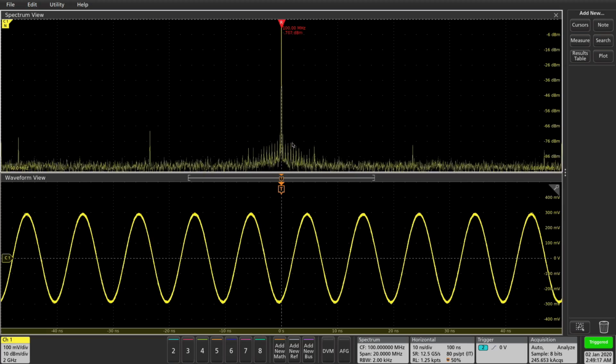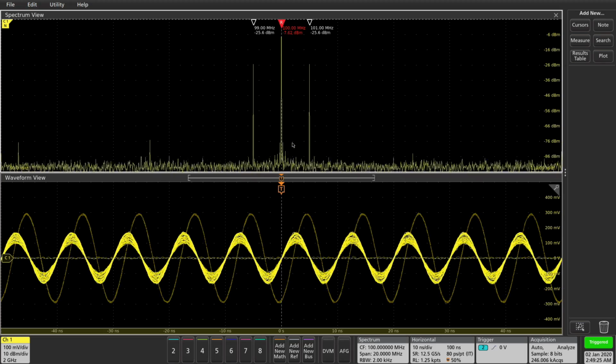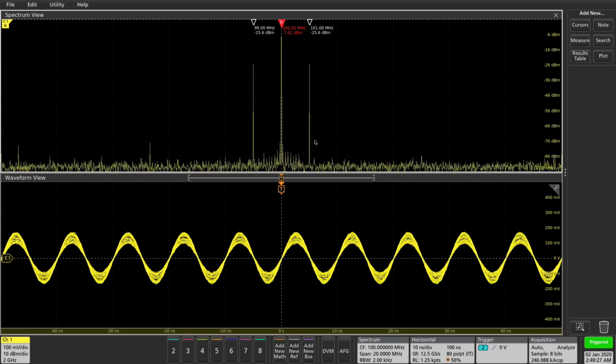Okay, that looks good. So now we can go ahead and add AM modulation. Here it is. Here's our AM modulation. This is a 1 MHz modulated signal, and the depth of the AM modulation is 25%. So you can see, if you look at the top and the bottom of the sinusoid, very clearly we have some smearing, or we can clearly see that there is noise added.